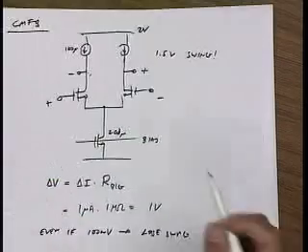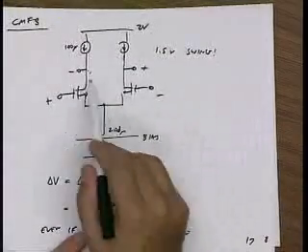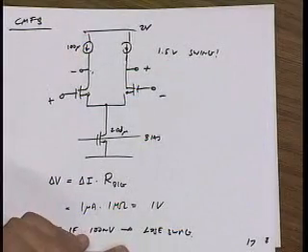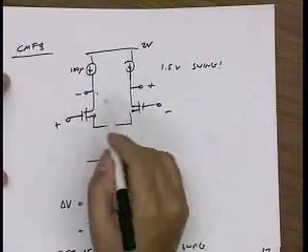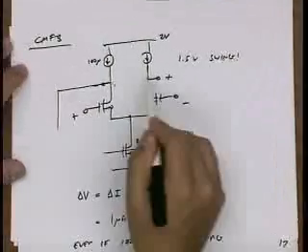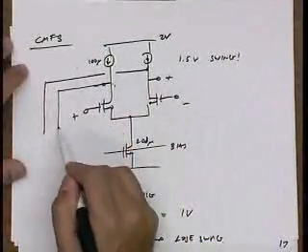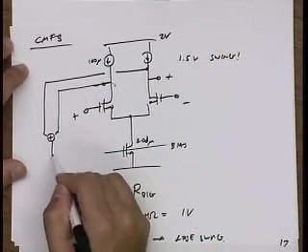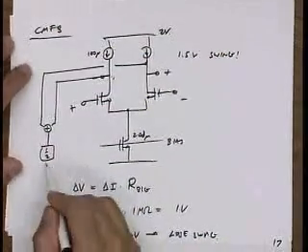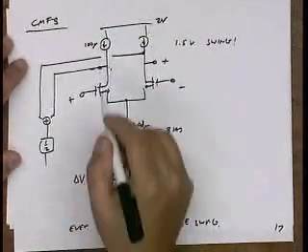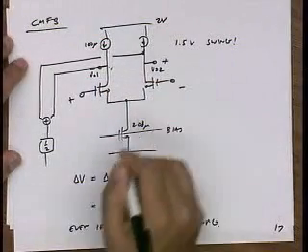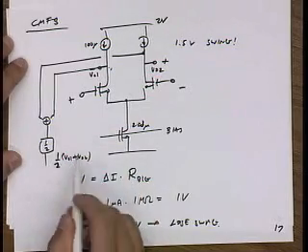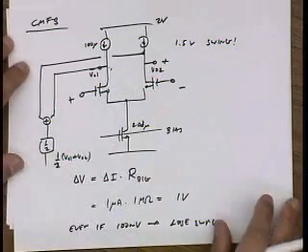So the idea is that we do need a feedback loop to fix the common mode voltage here, let's say within tens of millivolts or better, so that we don't really hurt our swing. So all I really need to do is take these 2 outputs, let's say sum them, multiply by 1/2, and that's the common mode voltage. This is VO1, VO2. This would be 1/2 VO1 plus VO2. That's the actual common mode voltage, right?